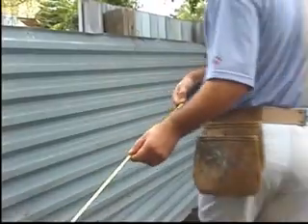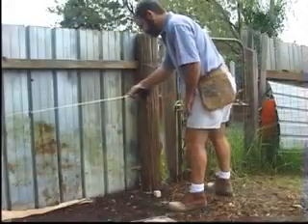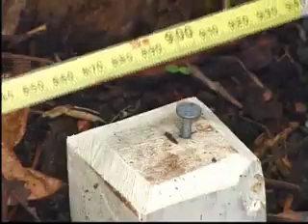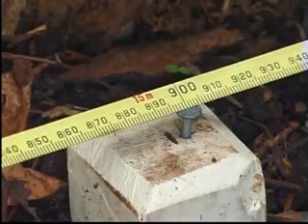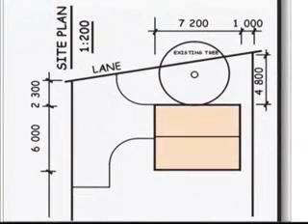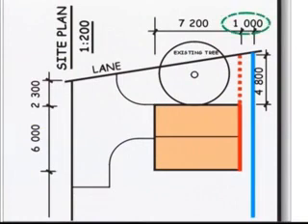Buildings are often located parallel to one side boundary at a specified setback distance from that boundary. A second setback from the front or rear boundary is needed to site the building. The combination of the two setbacks fixes one corner of the structure.